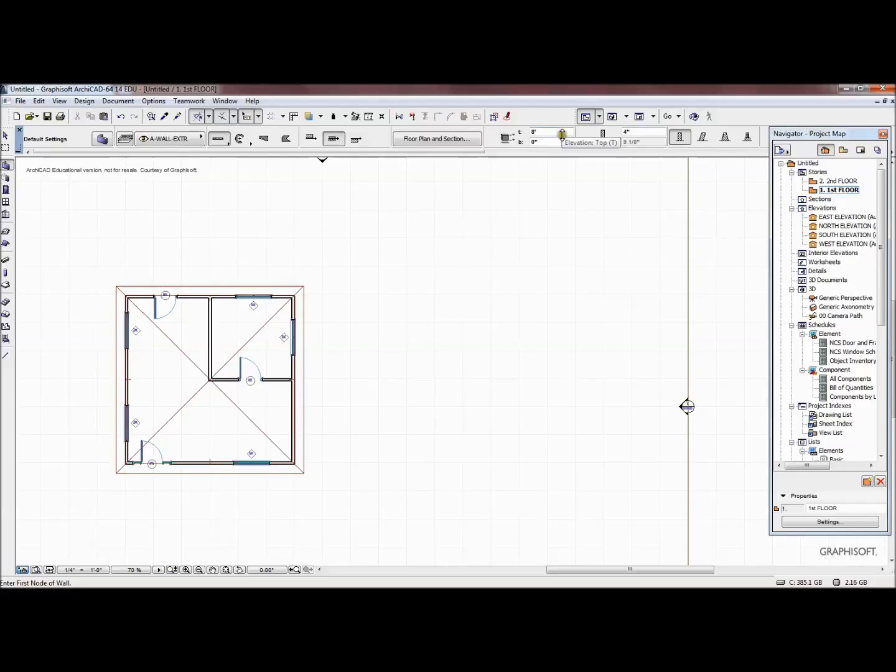You can not only double click on the wall settings, but you can also change those settings in this ribbon. So what I'll do first is hover over this corner, and you'll see some blue dashed lines that come up. Those are called intuition lines, and so I will hover over those again to get them to show up. If you stay right on those, it will hold you in that position. Then when you click, it will start in that position.